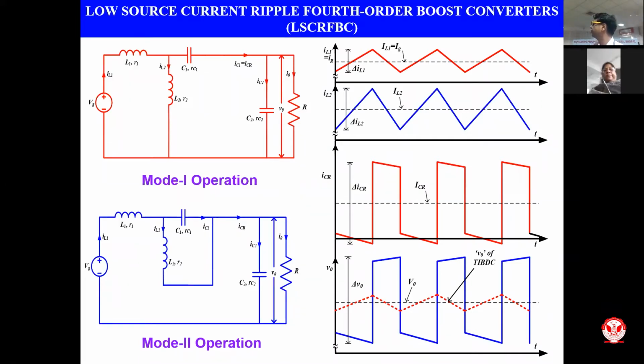on the source side. So interestingly, in the first two converters you were able to see that it was improving source as well as load side performance, but this converter is not suitable from the load side aspects, though it's quite beneficial in terms of interfacing either a battery as an input or the solar panel as an input.